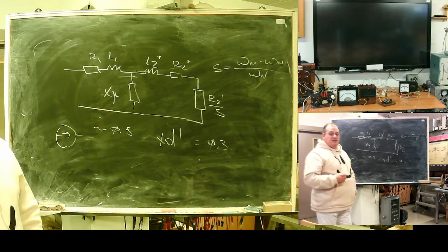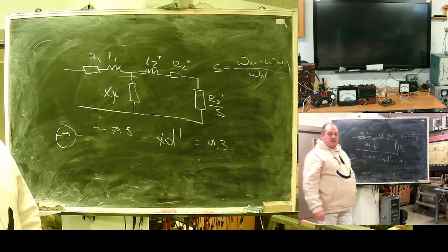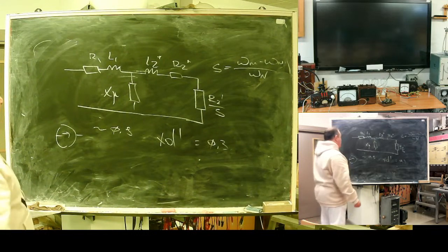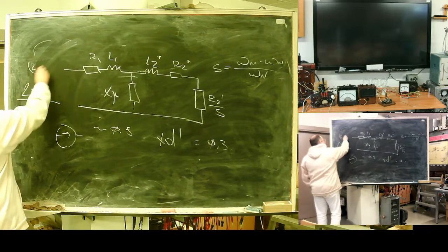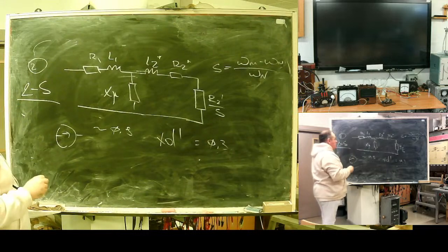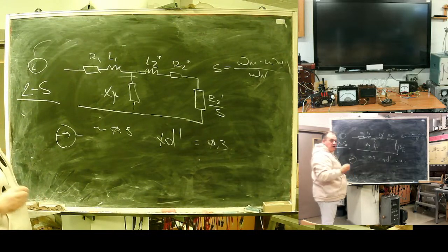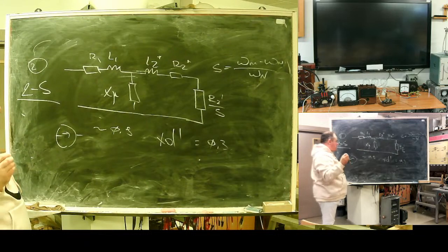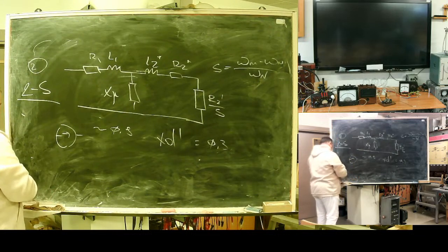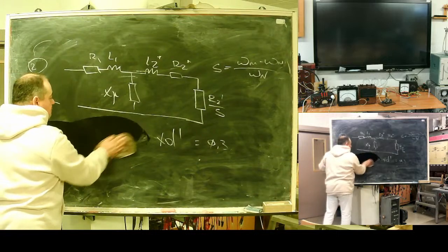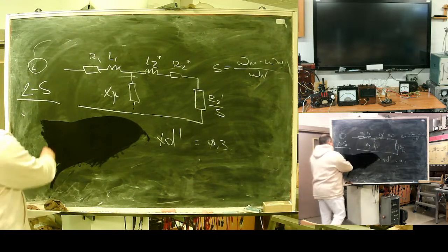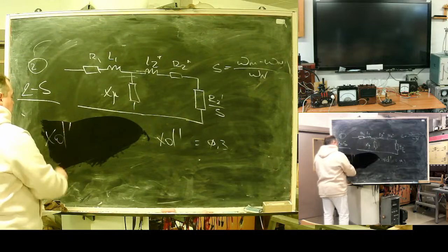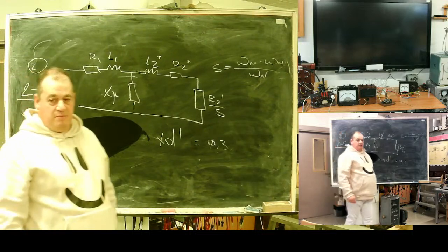In case of negative sequence, and asynchronous machines don't like that, you will have not S, but 2 minus S. For some machines, this data of negative sequence reactance is available, but not for all. If you got it, good. If not, just take transient reactance and it will be okay.